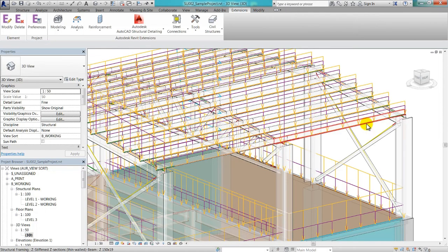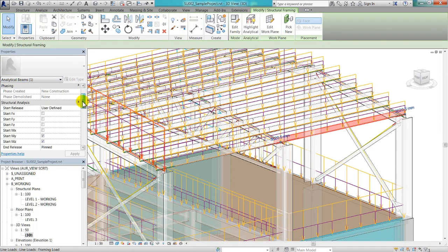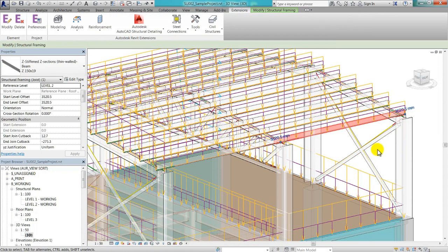The modules will recognize the structural definitions from the analytical Revit model. They also offer the option to change existing, apply additional, and delete unnecessary supports and loads. Take particular care in defining loads, supports, and bar end releases properly. This can be done either by adjusting the Revit analytical model or by changing definitions in the analysis dialogues.